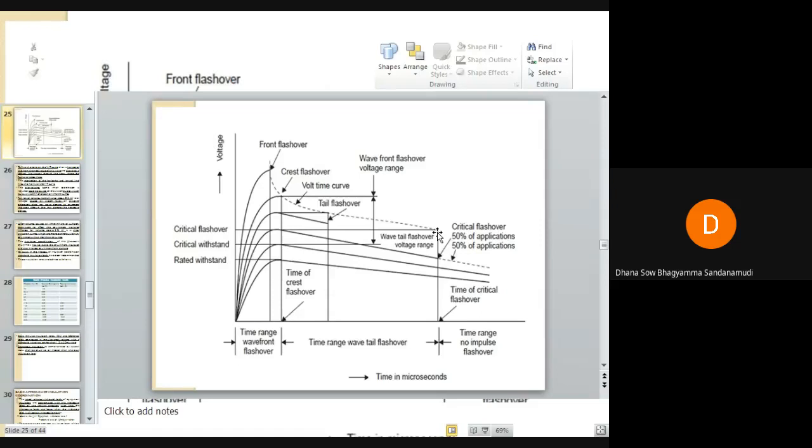Fault cannot be specified. Just for example, let us assume that the overvoltage is up to 345 kilovolts. Based on the analysis and study, what the engineers have found is that if the overvoltage magnitude is up to 345 kilovolts, that overvoltage may be caused due to a system fault, a fault within the system. Faults within the system are LL, LG, LLL or LLG. It can be any fault, or a fault during switching operation.